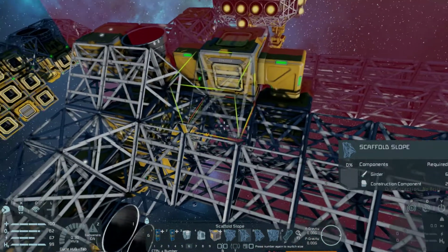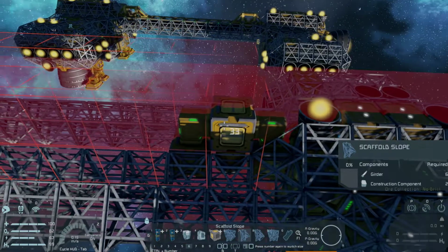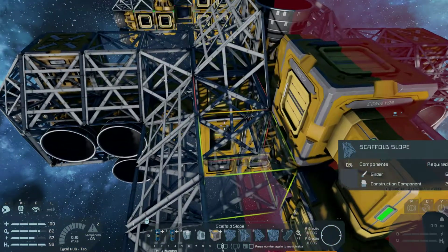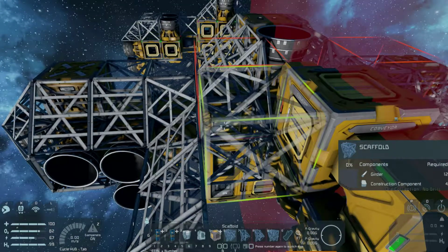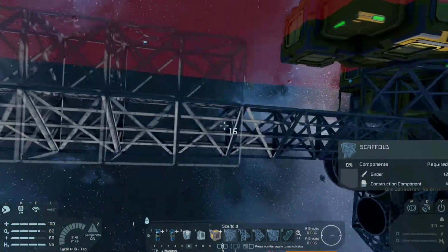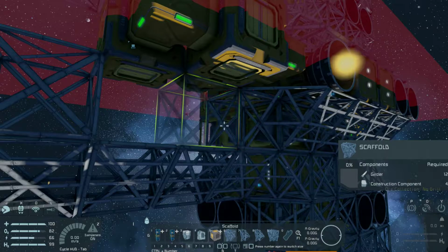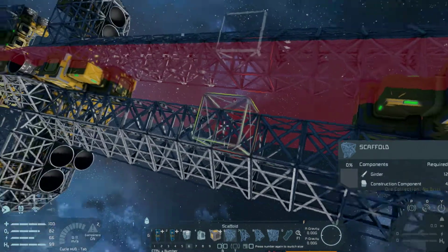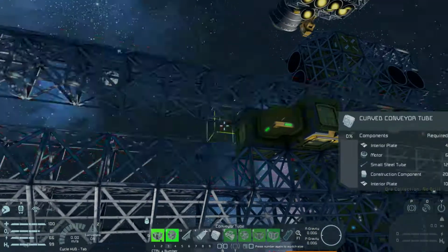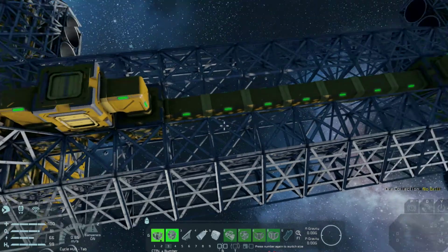I'm going to delete all of this framing all the way through. Delete. Alright, and then I'm going to change this one out to be a full block. Which just changes the other side, which means this can change to full blocks all the way down. I'm going to stop with that one because I need to change this one out to a full block as well. And then block. Alright, now with a little bit more frame, I feel a bit more comfortable in adding in my generic piping. There we go.